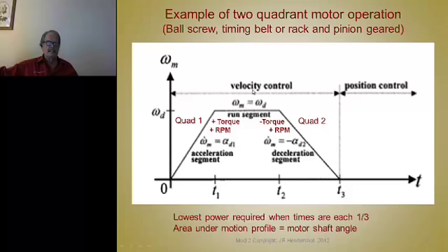We would come up like this and hit a point and then decide we have to stop and then reverse torque, make torque negative, and stop and come down till we get to here. So we'd have a triangular move where the area in this peak of the triangle equals the two areas we lose over here. Now, if I could accelerate in 0 time and get to a lower speed and stop in 0 time, the area underneath that rectangular move would be equal to the same area as this.